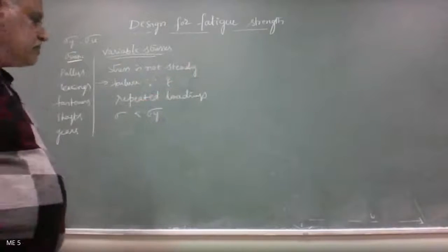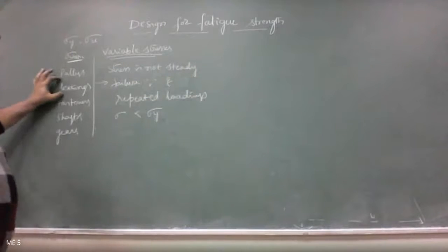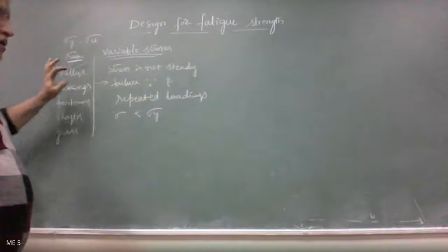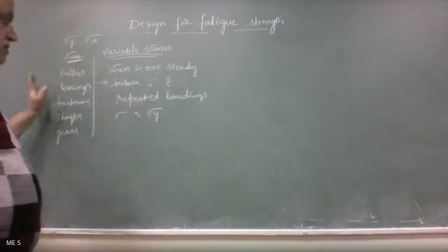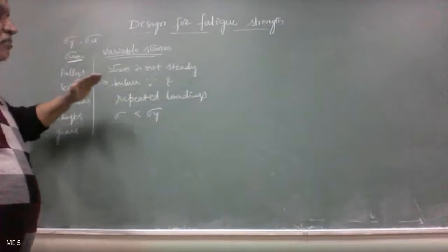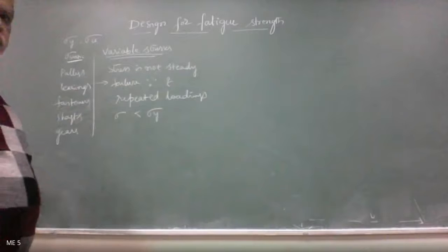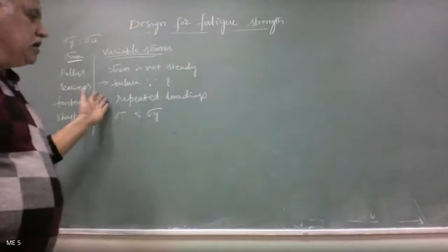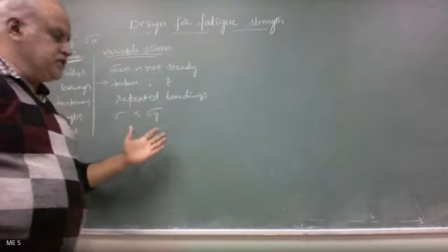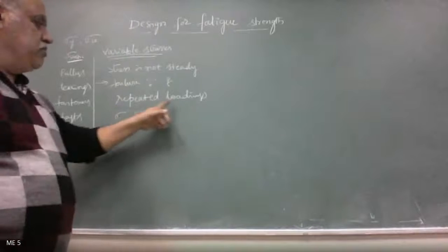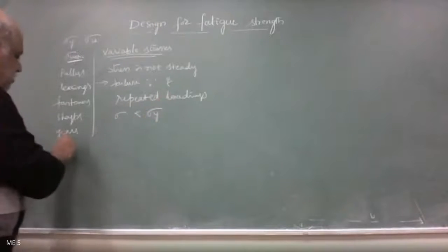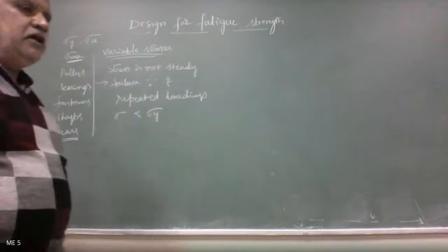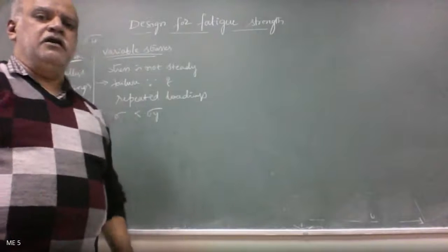If you take a bearing, for example, it may not fail in 1 day or 1000 cycles. It may fail over a period of time because of repeated loadings, maybe after some 10 power 5 cycles. When you talk of gears, they may not fail in 2 or 3 days or in 1 lakh cycles.